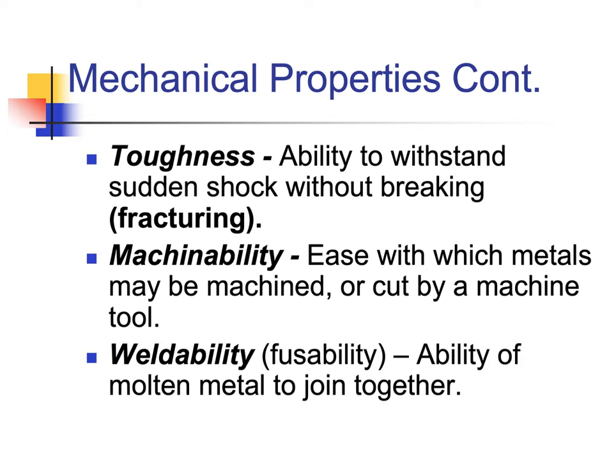And then weldability is the ability of molten metal to join together. So some materials are not very weldable, and an example might be cast iron. If anyone ever broke an engine block or something like that, and you try to weld it together, if you don't know what you're doing, you can definitely just continue that crack further along.